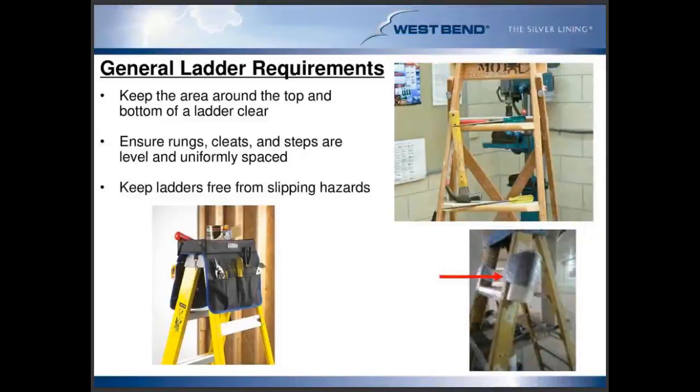From general ladder requirements, we always want to make sure that we're keeping the area around the top and the bottom of the ladder clear. Obviously, on the bottom of the ladder, there's a slip, trip, fall potential. If we have debris or tools as we're getting down from the ladder, the last thing we want to do is trip and fall in them. When we're storing tools and materials like in that top right-hand picture up on an elevated rung, there's a potential for not only a slip, trip, fall, but also a struck-by potential if that hammer were to come down and land on somebody's foot.